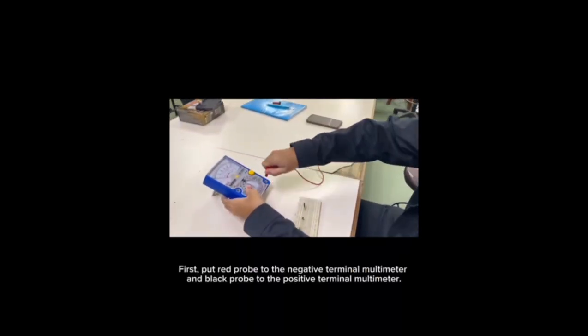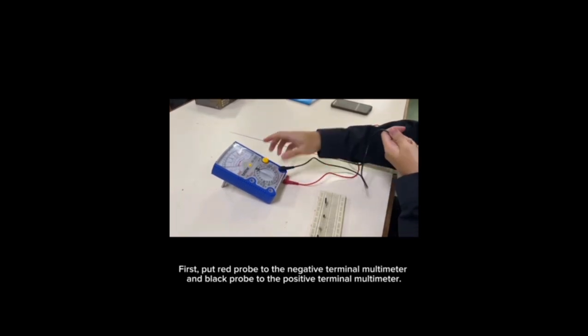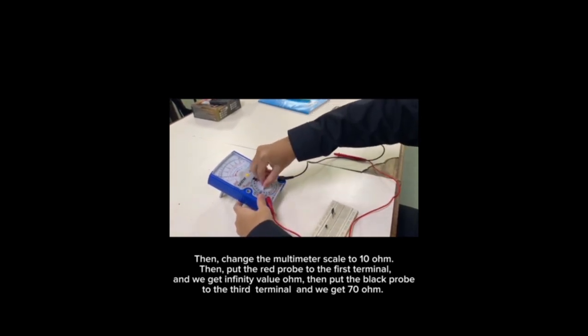This is BD140 and I will demonstrate step by step how to determine the type of transistor and its terminals. First, put the red probe to the negative terminal of the multimeter and the black probe to the positive terminal. Then change the multimeter scale to 10 ohm.